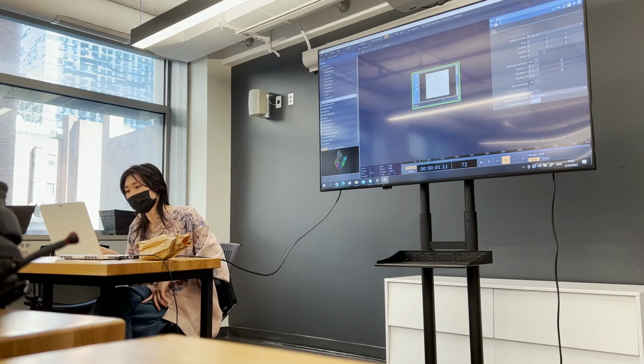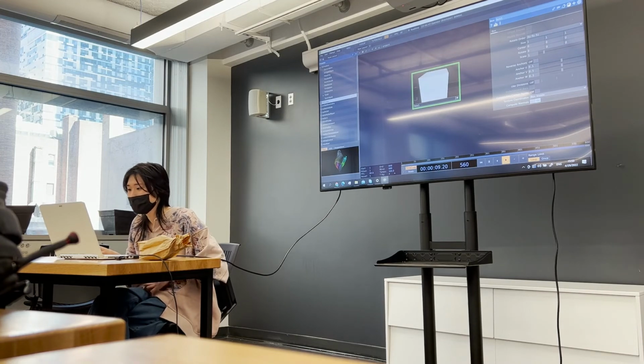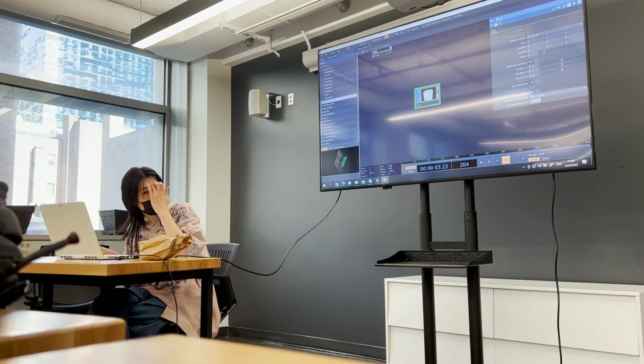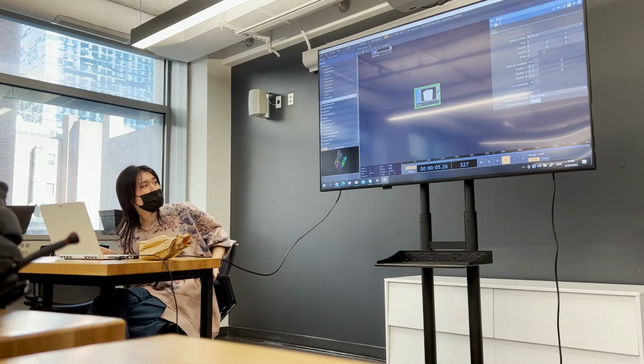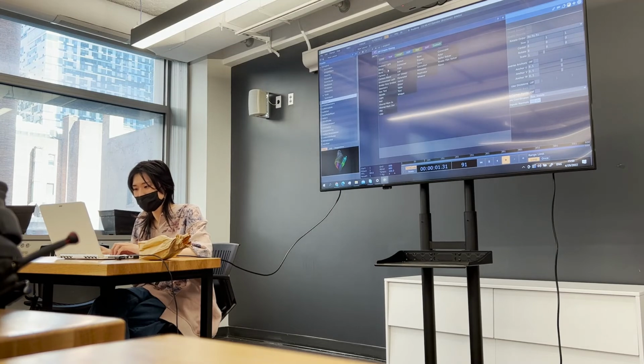If you click on the viewer active, we can navigate. Click on this viewer node, we can navigate in 3D space to look at it. It's not going to change its transform or anything, just looking at it. And to see it, there is quite a lot of setup in here. So first we need a comp that's called geometry.